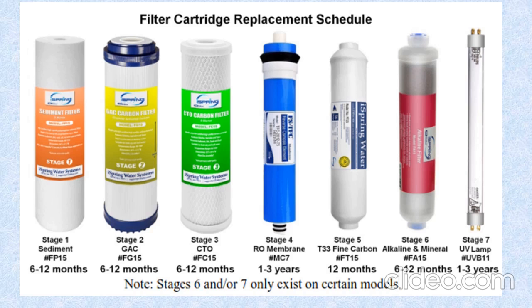And stage 7 is also not available in every unit. Where you want to kill the germs in the water, we have this UV lamp. The UV lamp glows, kills the germs in the water, and purifies it. So here stage 3, stage 6, and stage 7 are optional in any filter. It depends upon the need of the person or the place where the water is to be used, and accordingly we fit them in. So when we say reverse osmosis, it is not only the membrane; see how many filters we have used. Everything plays a role in it.